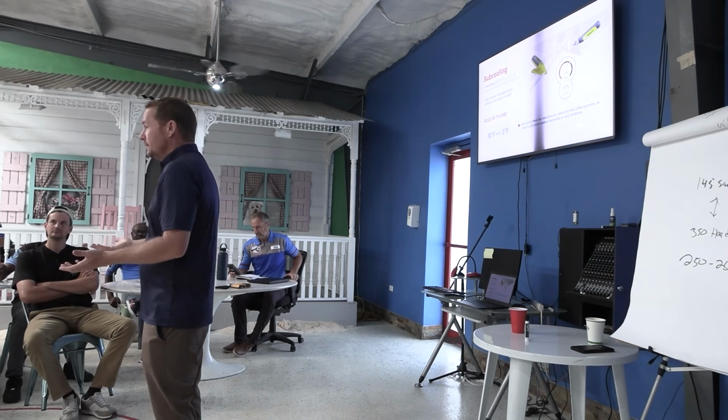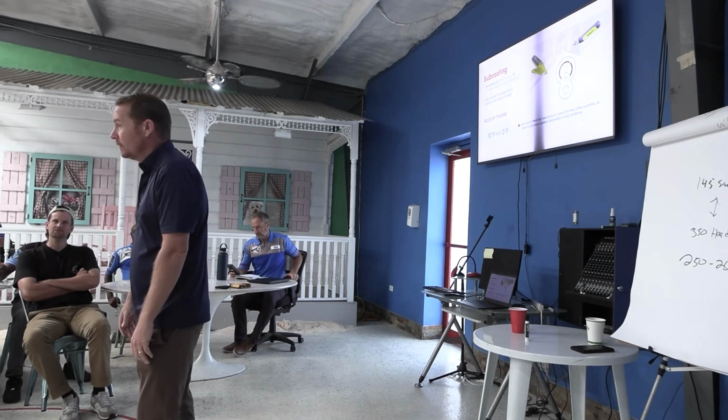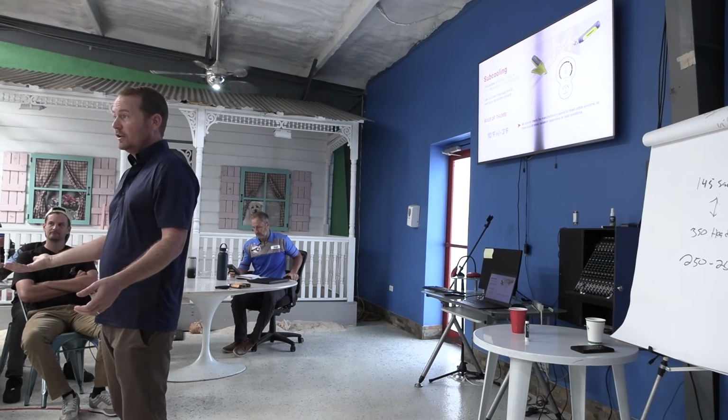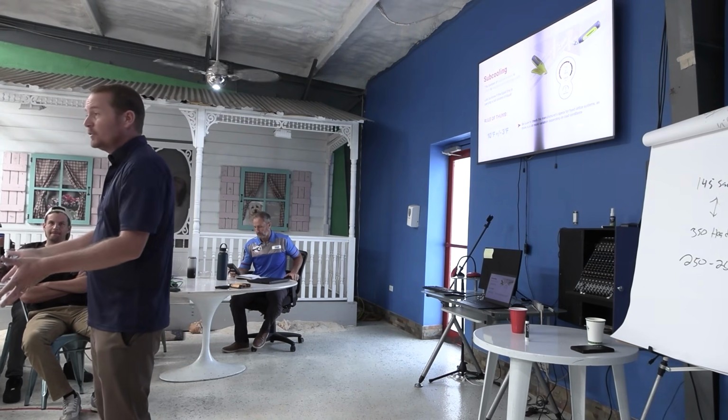You walk up to a unit, and you know it's in high stage, or at least it's supposed to be, and you can't hear it running. Like it's barely running, and you're used to these units. You work on them all the time. You know there's always a little whistle, you can hear the thing, and you don't hear anything. The return's quiet, right?